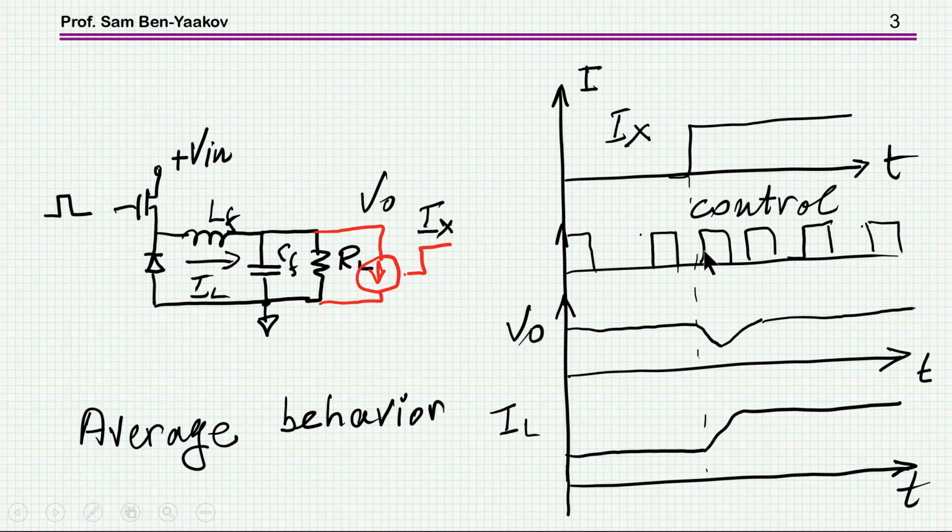current to go up. So what we're going to see here is, initially, as the change is occurring, there's going to be a drop at V out, but at this point the current of the inductor starts ramping up. Here it is, and consequently it'll correct this drop, and eventually will come to the same value, assuming, of course, that the system is working in closed loop. I'm talking about closed loop operation. I'm not showing it here at this point. So this is the average behavior of the system.